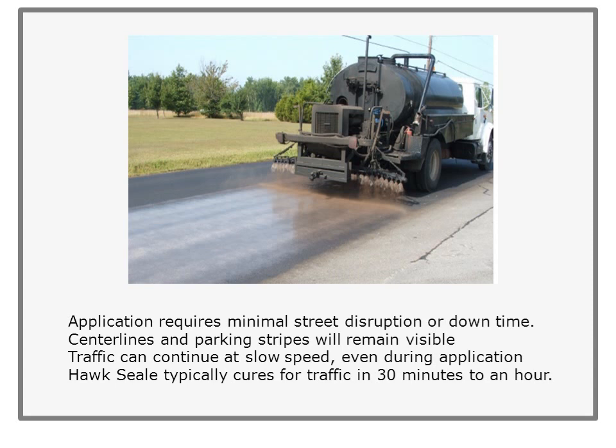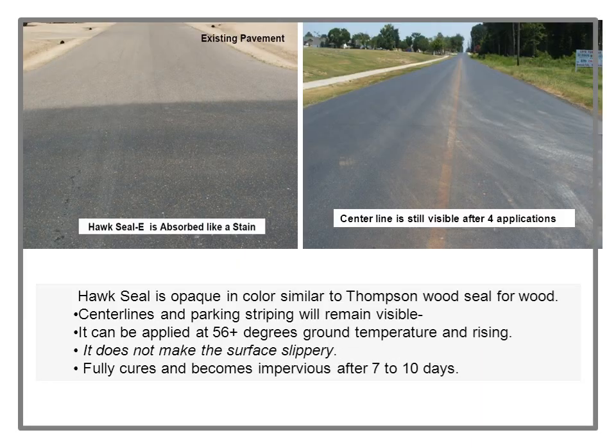Application requires minimal street disruption or downtime, and the center lines and parking stripes will remain visible, and traffic can continue at a slow speed even during application. And Hawk Seal typically cures for traffic in 30 minutes to an hour depending on temperature. Hawk Seal is opaque in color, similar to Thompson Wood Seal for wood, and the center lines and parking stripes